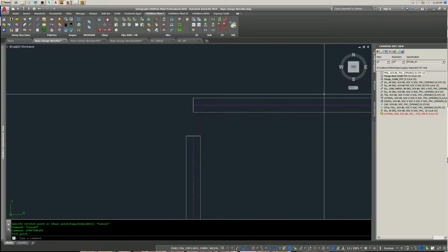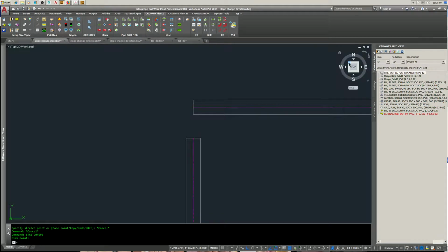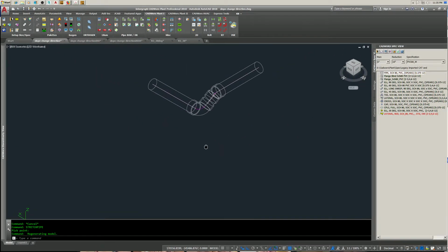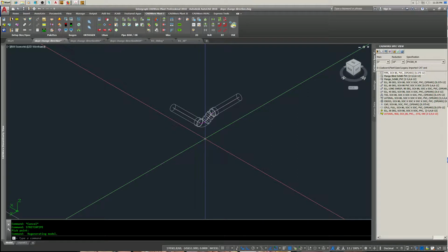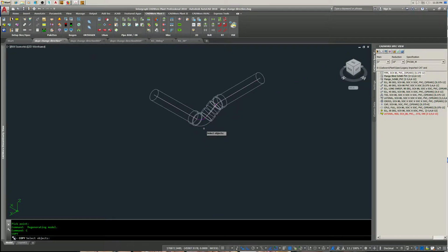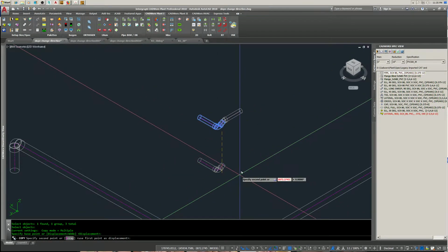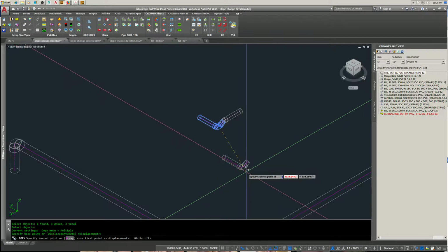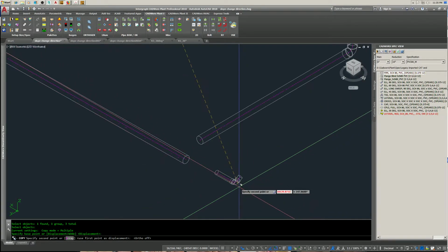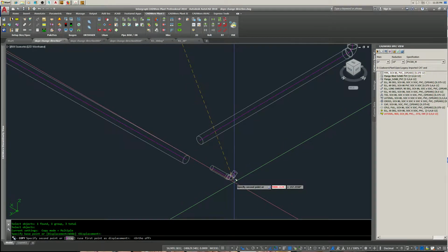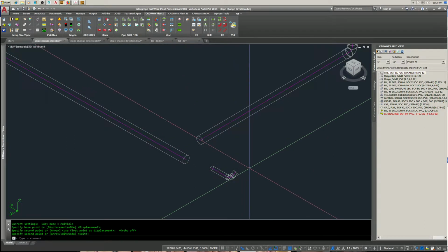In Navisworks, the dimension function for the XY dimensions is useless. The only thing that works is the height or the z-axis.